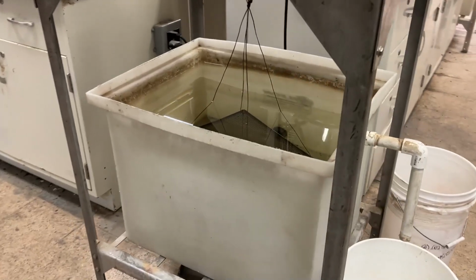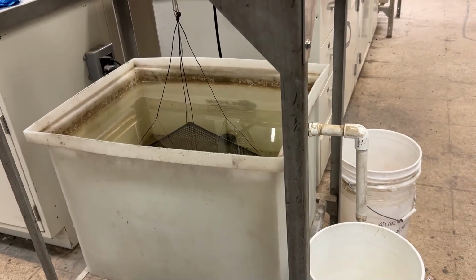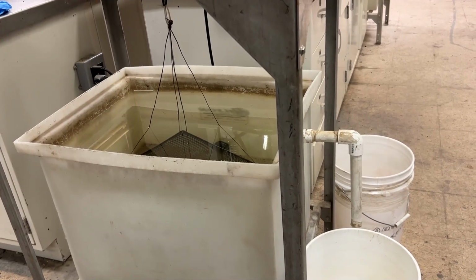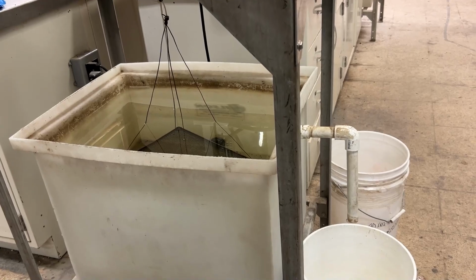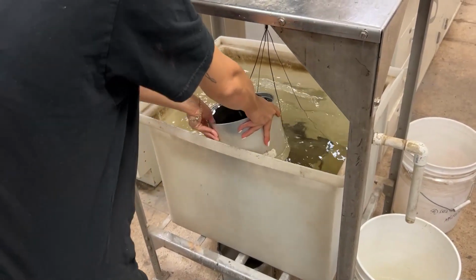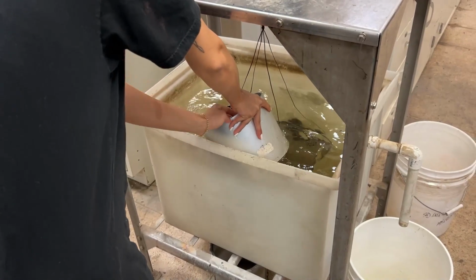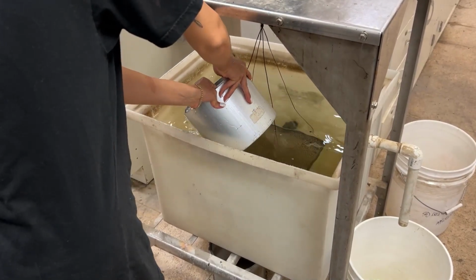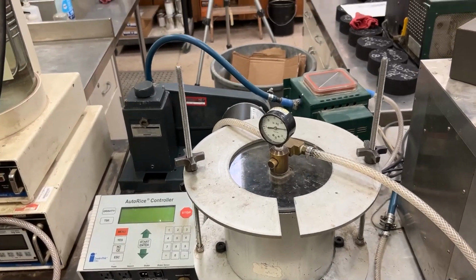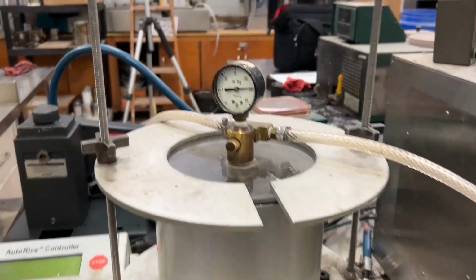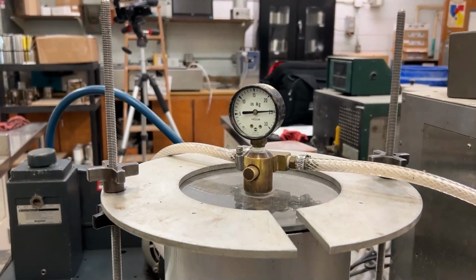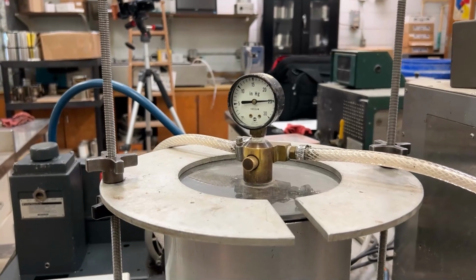For the mass determination in water, the ballast shall be equipped with a suitable apparatus and holder to determine the mass of the sample while suspended below the ballast. A water bath capable of maintaining a uniform temperature to determine the mass in water at 25 plus or minus 1 degree Celsius. A vacuum pump capable of emptying air from the vacuum container to a residual pressure of 3.4 kilopascals or 25 millimeters of mercury.